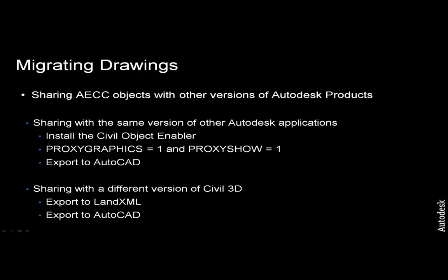Finally, the Export to AutoCAD command is available if you just want to save your Civil 3D drawing as a primitive AutoCAD drawing. It is important to note that this will explode all of your civil objects and they will lose their intelligence. So there is no coming back from the export to AutoCAD back into Civil 3D and expecting to see your civil objects and the intelligence associated with them.